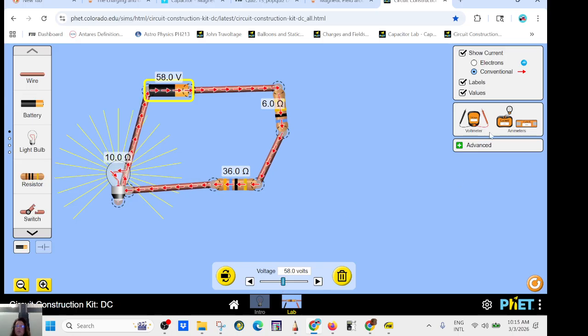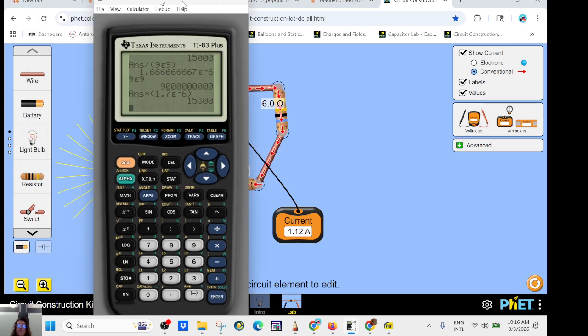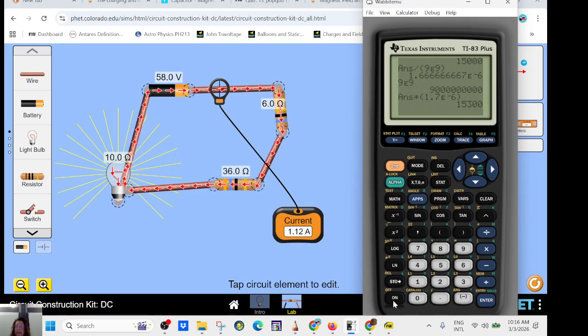58 volt. So first of all, in a circuit in series, the current will be the same everywhere. So if you want to know the current flowing through that circuit, you say everything happens like you have an equivalent load of resistance 6 plus 36 plus 10.